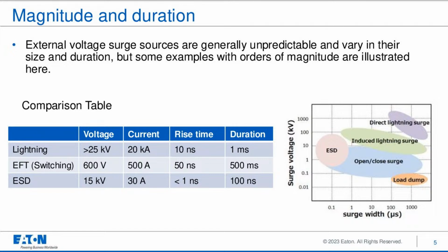Switching surges are caused by induced transients in a switch or relay during its open and close, off and on operation. Switching off can be particularly troublesome, which causes a rapid current change and inductance in the circuit or wiring. The voltage generated by an open-close surge can reach hundreds of volts and has the potential to generate a spark.